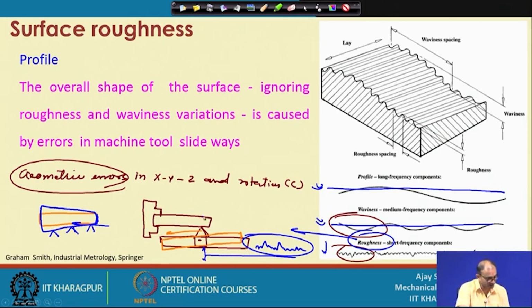If you see optical materials, when light passes through them, if it is a mirror, then it will reflect, and if it is a lens, then it will pass through it. So, if the roughness is as low as possible, the homogeneity of the light passing through or reflected from the surface of the optical material will have the perfectly required dimension, but that depends on the surface roughness. So, smaller the roughness, better is the performance in many cases, but not always. In some cases you always need a surface roughness also. So, that is a different case.